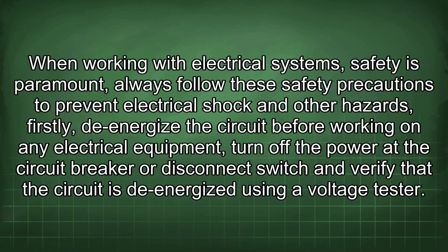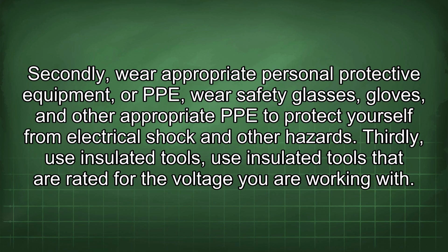Secondly, wear appropriate personal protective equipment, or PPE. Wear safety glasses, gloves, and other appropriate PPE to protect yourself from electrical shock and other hazards. Thirdly, use insulated tools. Use insulated tools that are rated for the voltage you are working with.